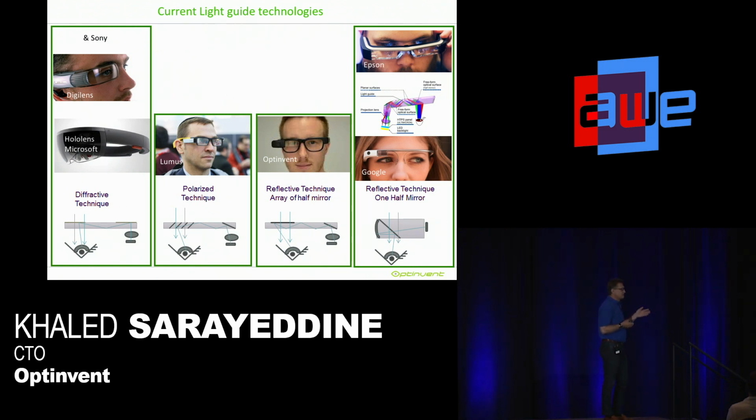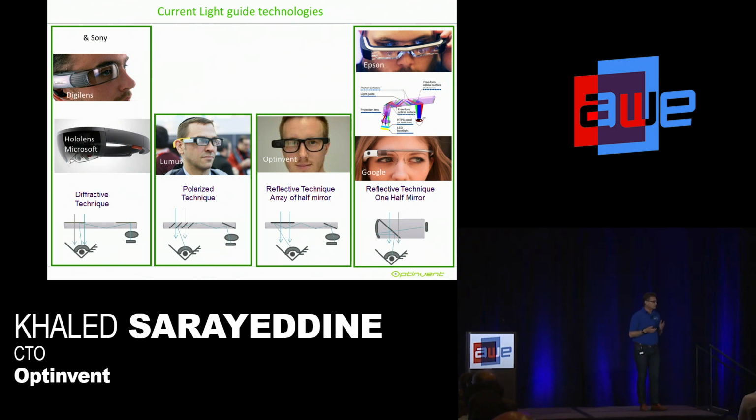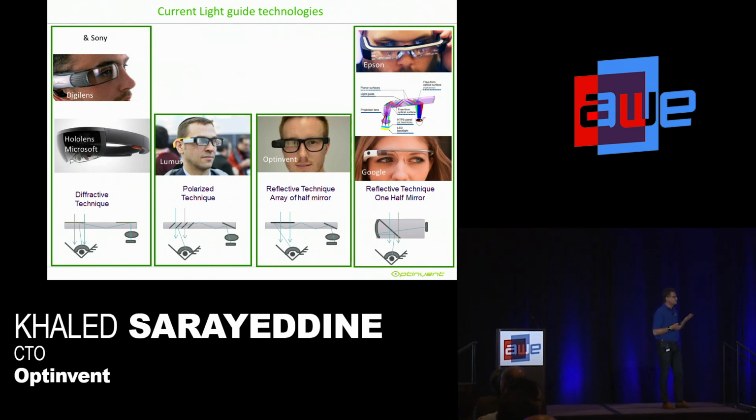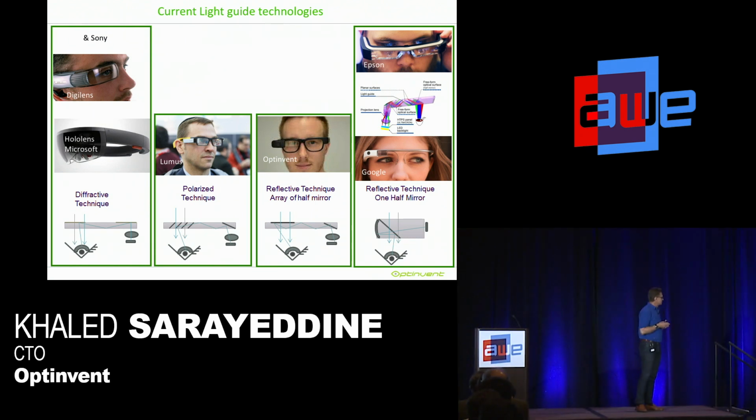It has a very high transmission ratio, up to 85%. It's very good. However, today, this technique needs 3 light guides, 1 for each color. If you look at HoloLens, they even have 4 light guides. So it's very complicated for assembly and still limited in field of view, except for DigiLens technology, where they are using a photopolymer, switchable, with high modulation for the material.